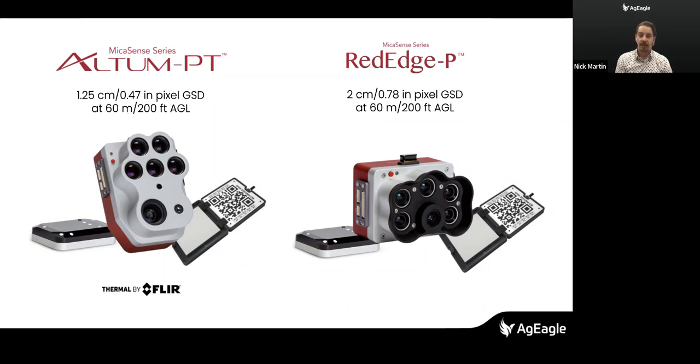So the sensor kits, and this is actually very important, MicaSense offers double calibration. What's better than single calibration? Double calibration. So we calibrate our sensors in two different ways. Before you fly a mission, you'll take an image of the calibrated reflectance panel, which is right here, which will effectively calibrate the different bands based on the environmental conditions, the ambient conditions happening at that moment.